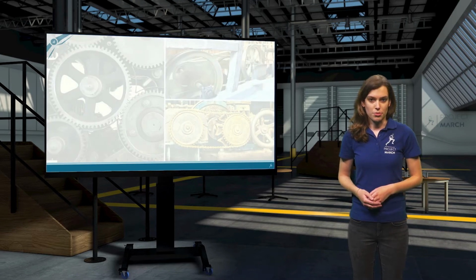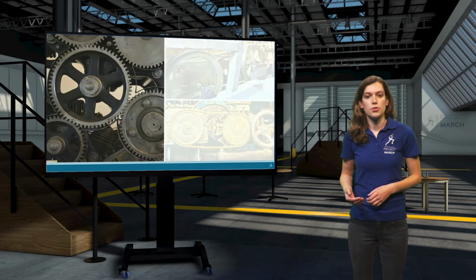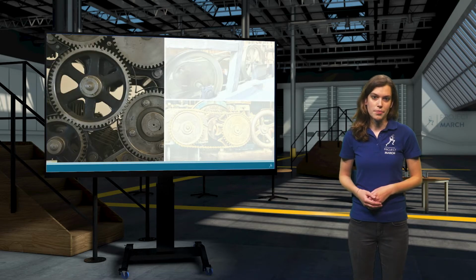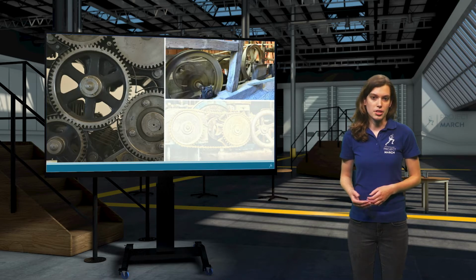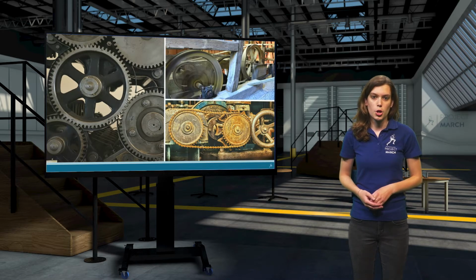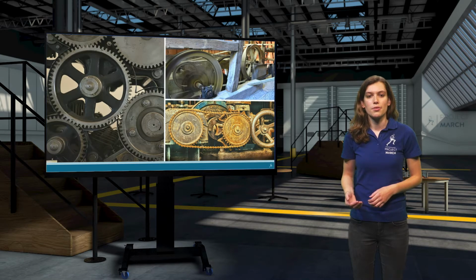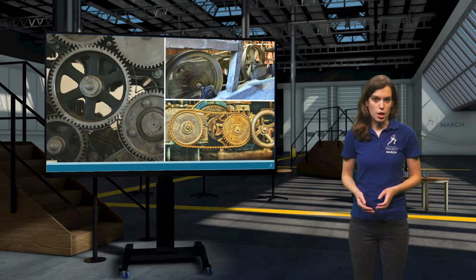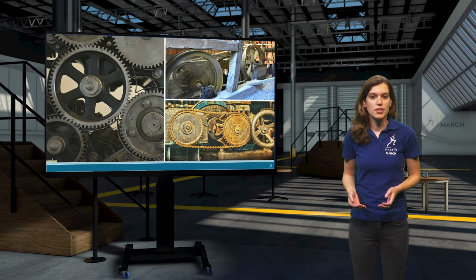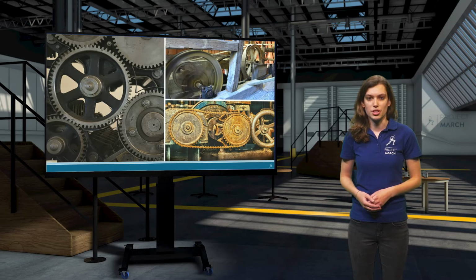There are different types of transmissions. Common drive elements that are used are a gear drive, which is used in, for example, old-fashioned watches, a belt drive, commonly used in mills, or a chain drive, which you might recognize from your bike. They all have their own advantages and disadvantages. For example, how well it can absorb vibrations, how well it can transfer heavy loads, and if it can handle fast speed reductions. In our exoskeleton, we use a special type of gear drive.